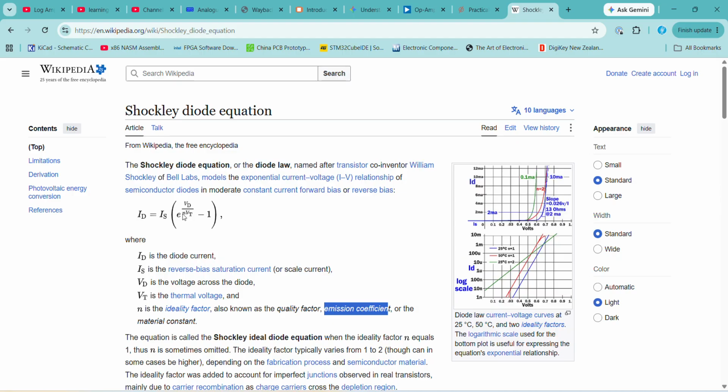So when the current is small across the diode, what happens is the recombination in the p-n junction, its depletion region, which is basically a minority carrier charge flies through and then it falls into a hole. So a lot of recombination happens compared to diffusion, which is the charges flying straight through. So when the current is low, the holes are not saturated, so there's a lot of recombination happening. And with diodes, this changes this emission coefficient.